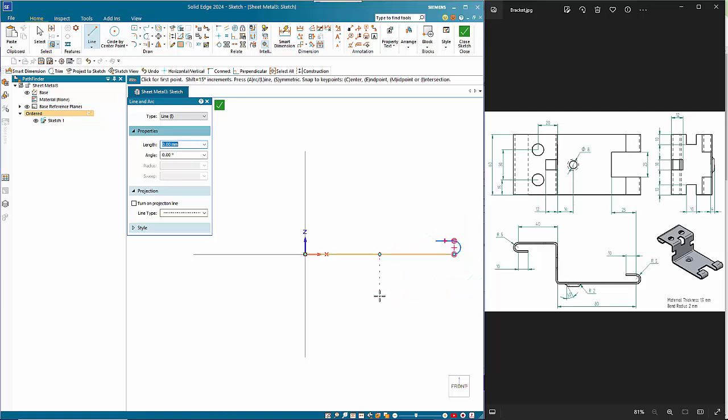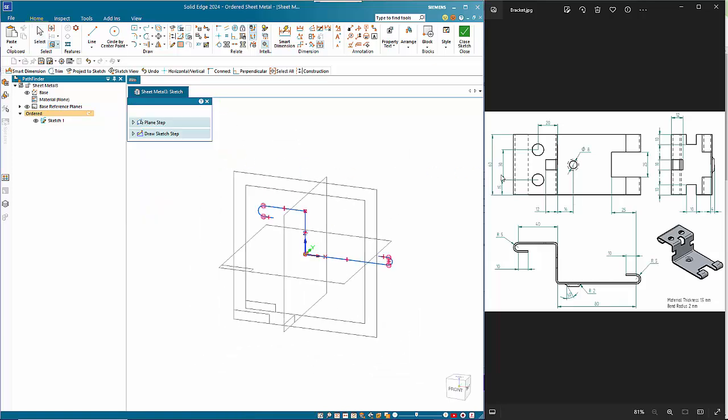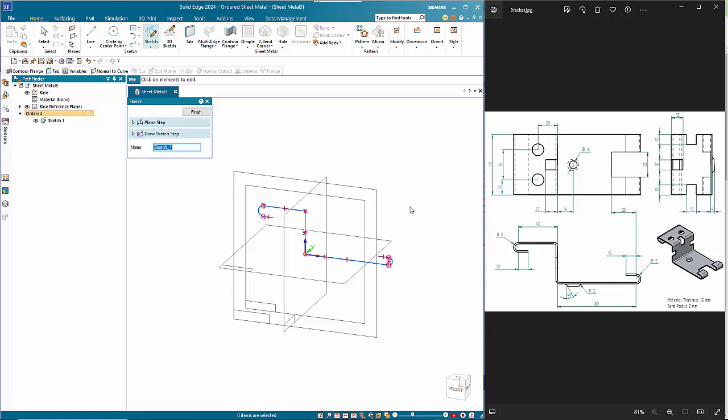and then we've got a 10mm flange coming back. So I've done a reset, which is a right mouse click, and then I can go in the opposite direction and start putting in those other values there. Again, the A key to take me into an arc, and this time it's the outside rad, so this wants to be 5, and a 10mm length on that hem in there. So that creates my profile, so I'll accept that, and the width on this is 60.